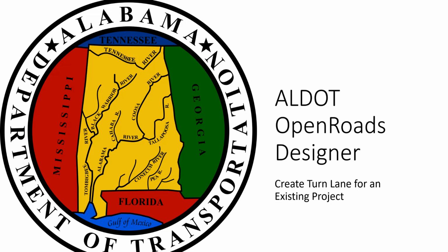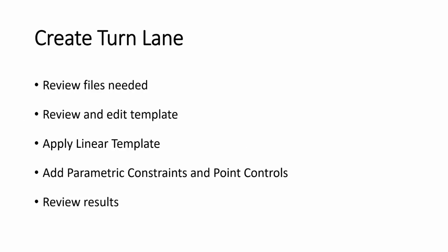In this video, I will demonstrate how to create a turn lane for an existing or standalone project. In creating a turn lane, we will first review the files needed. We're going to review and edit our template. We will apply a linear template, add parametric constraints and point controls, and finally, review our results.